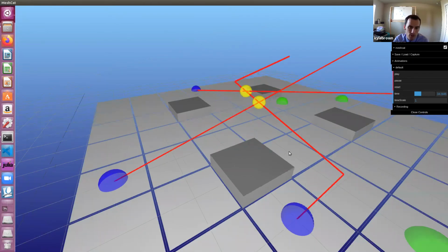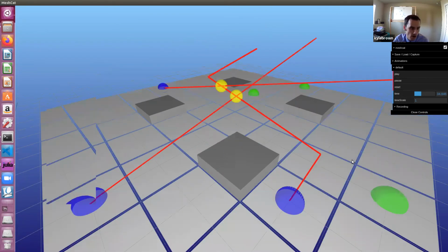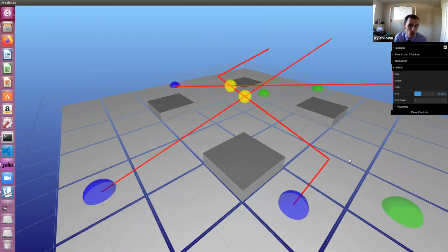And the reason we have 2 collisions here is because A* is completely ignorant that there are 2 paths already planned for other robots, and we should be trying to avoid collision with them. One simple way to augment A* is to add a tie-breaking function to the cost function so that it breaks ties for search states in favor of those that don't have collisions. So we watch again, same algorithm, but now with a tie-breaking cost function added to it.